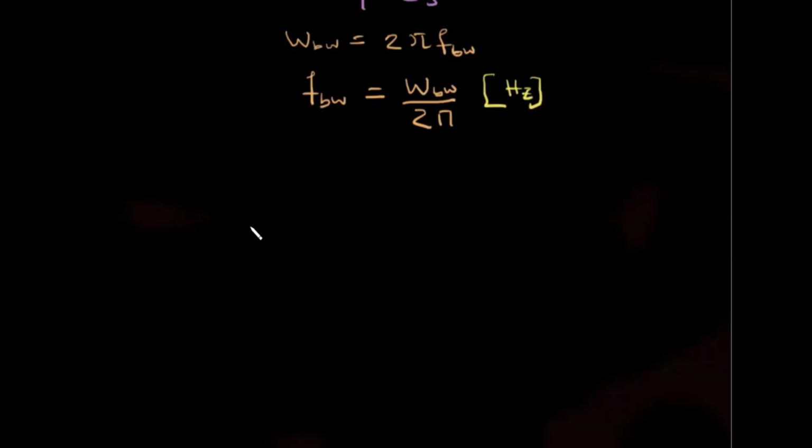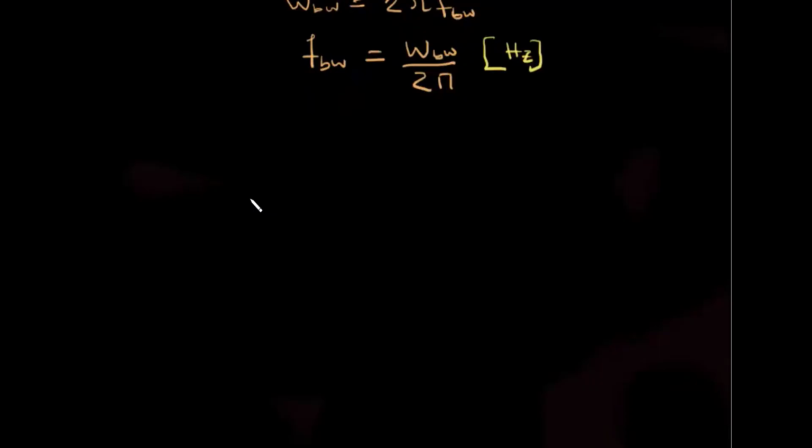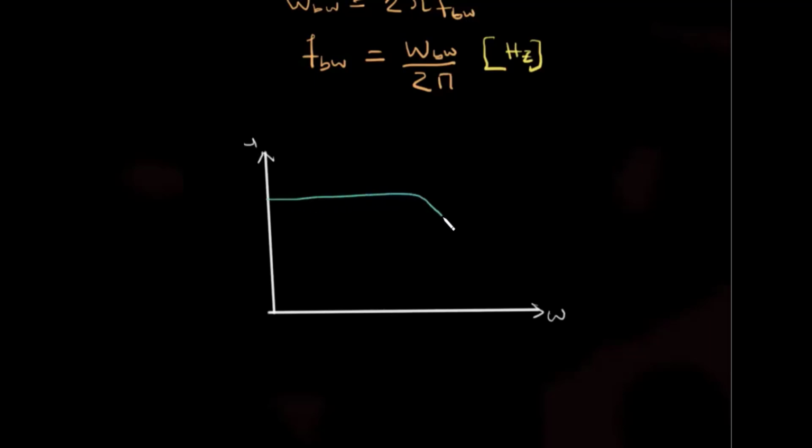So for our first order control system shown here, if we do a Bode plot, or a plot diagram here, with omega and this is our magnitude, we will have the following characteristics. If this one here is my omega bandwidth, and I go up here and then to the left, to my magnitude, this will give a magnitude of minus 3 decibels.